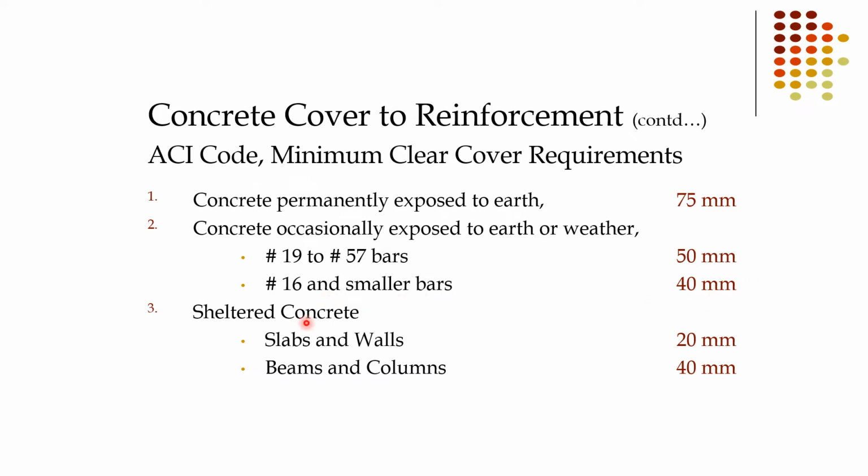For sheltered concrete, normally in plazas and residential buildings, for slabs and walls that should be 20 millimeter, and for beams and columns 40 millimeter. You should keep all these minimum covers in your mind because these are very important.